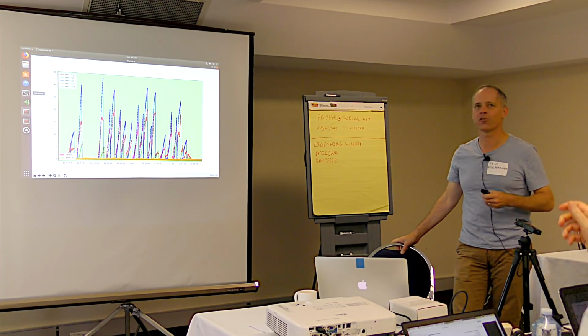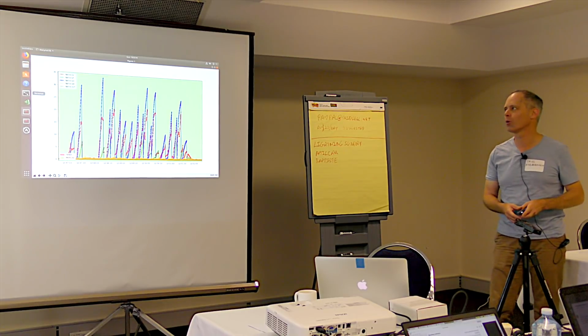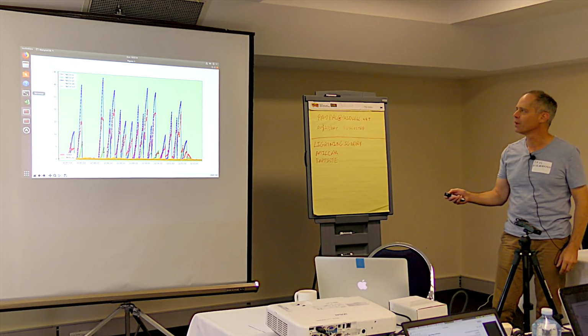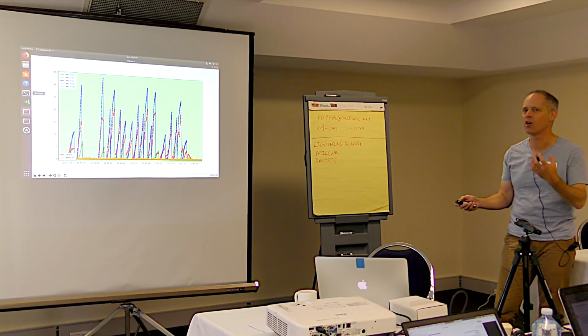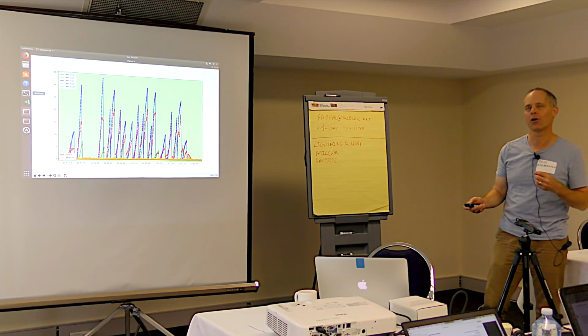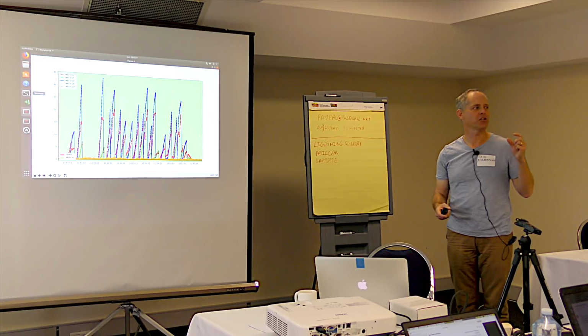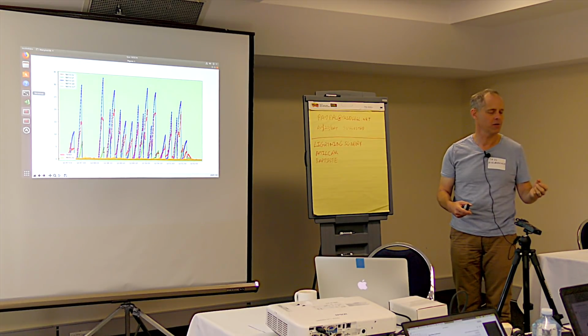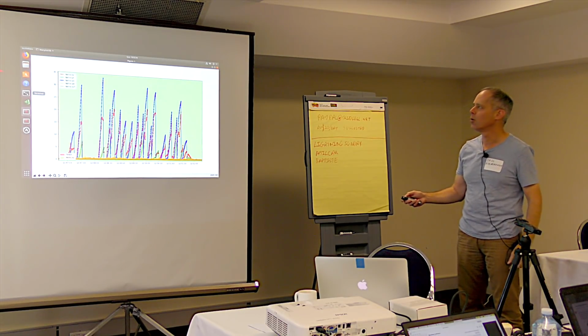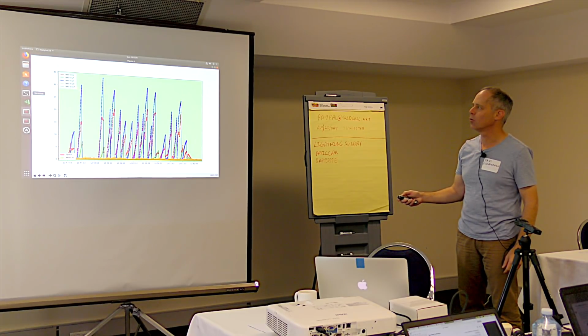So what's the first place you go to when you're looking at a log? Well, I go to these things people call variances, probably not a very good name. They're actually an overview of the innovations. We take the magnitude of the innovations for the GPS velocity, or the position, or the barometer for the height, velocity, position, height, or M for magnetometer, or VT for true airspeed. And these are available in Mission Planner.